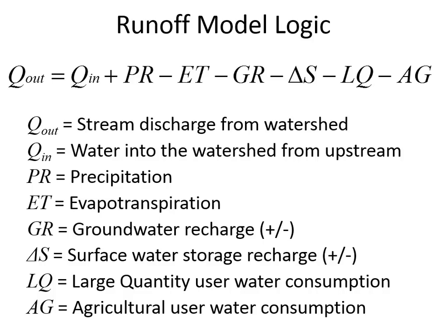What would happen if groundwater recharge wasn't steady over the long term? Like if there was a net positive or a net negative groundwater recharge? What would happen to the water table level if there's, over time, positive groundwater recharge? I mean, year to year to year. If there was a net positive recharge for multiple years, then the water table would be going higher and higher and higher, and eventually all of the soil would be fully saturated. And we know that that's not true.